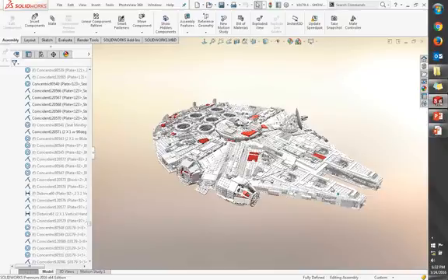And technically, I had a lot of arguments with my own engineering department about that as well, especially when we went to PDM. Someone had changed a part, and they came up to me and said, I didn't realize this, but I allotted 4 hours to change the part in the subassembly it's in, but when I did the where used in my PDM system, we found out that it was used in 40 different places. And now it was my fault that we went to PDM because I made more work. It's an argument that we had to have, and the only solution I could come up with is make a new part number.